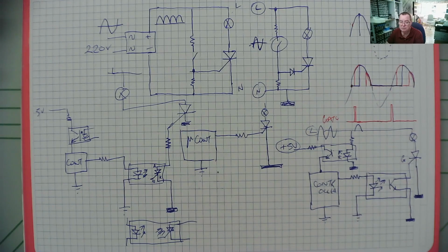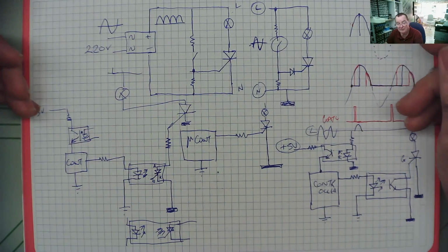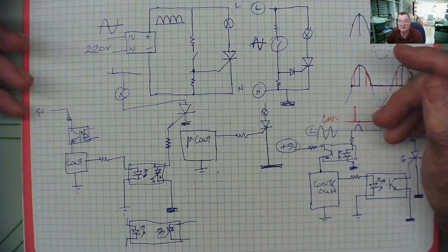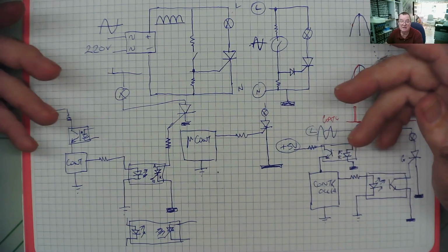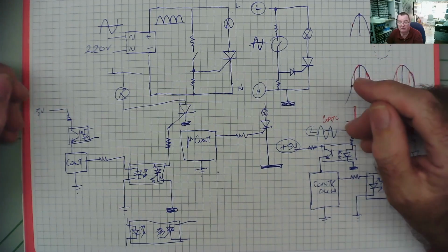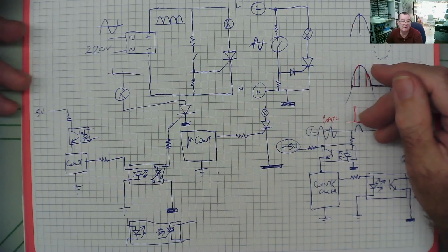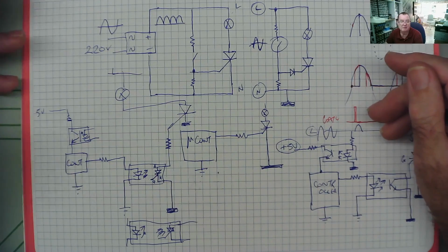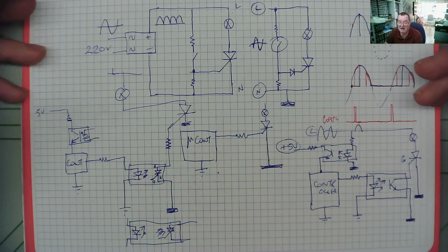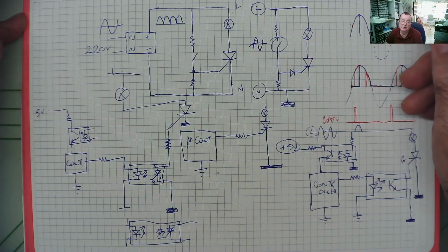They don't go lazy, if you like, whereby they lose their sensitivity, the amount of current or voltage needed to turn them on. But what you can find is a situation where somebody else has tried to repair an item and the thyristors or triacs have been replaced with the wrong type, which are not sensitive enough. You would normally know that because, as I was just doing with the handheld oscilloscope, and by the way, do not try that with a bench oscilloscope unless you understand grounding and ideally have an isolation transformer on your bench. You need a handheld scope for this type of work.